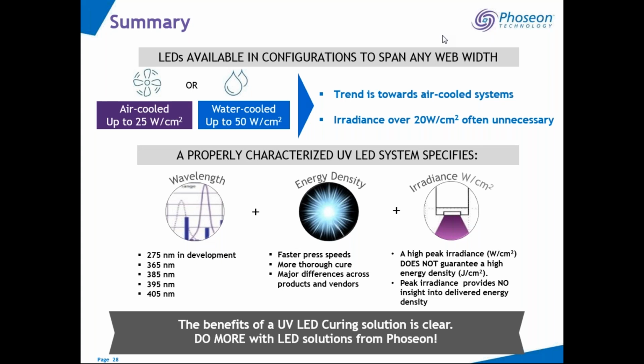And so why keep all of that infrastructure that's needed for a hybrid environment when, once you've dialed it in, and you should be able to do that very quickly, you can move forward with UV LED. Sarah, anything you want to add? Basically, as you said, it's the infrastructure, it's your air exhaust system, it's the maintenance that goes around the arc lamp, and so you're not really getting all of the benefits of the LED system if you're also having to deal with the drawbacks of the UV system. So we've seen the ink manufacturers and coating manufacturers all have LED solutions today, and so we don't see a reason to need to go backwards, like you said, to the traditional UV system.